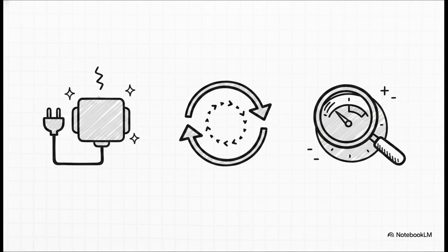Rule 2, is the loop present? If your robot does its action exactly once and then goes totally dead, you forgot your loop. Rule 3, are input data values correct? Did you tell the robot to look for a distance of less than 10 centimeters, or did you accidentally type greater than 10? A single backwards math symbol ruins the whole shebang.